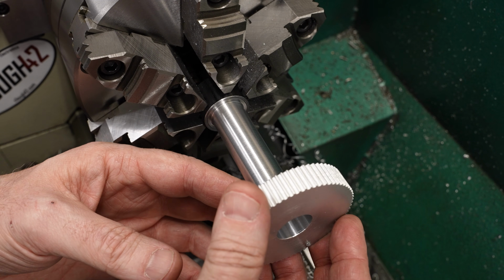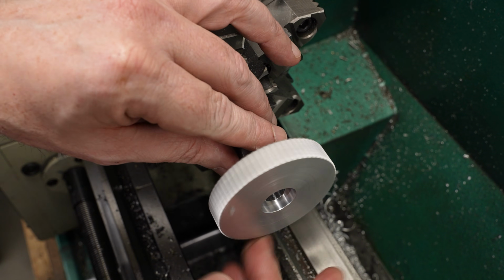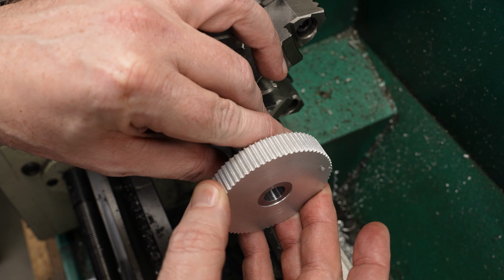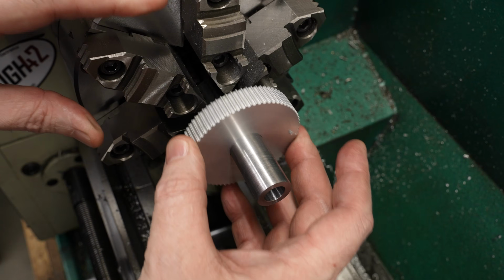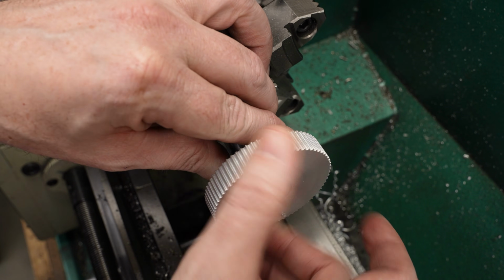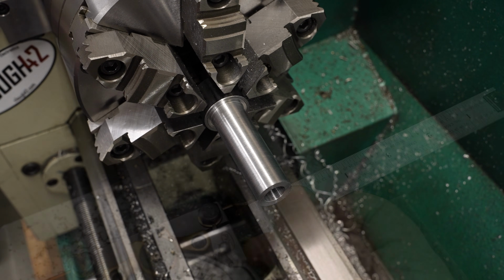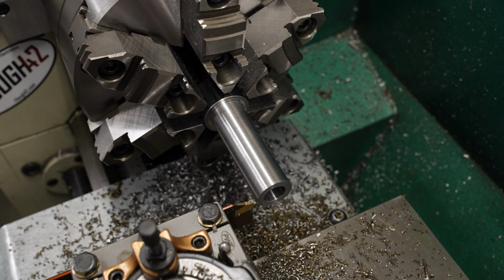And you'll remember that the pulley was slightly over, so there should be plenty of room in here for a retaining compound, but it should still be a pretty nice slip fit. And that feels pretty good. Yeah, I'm going to call that good. And there's not appreciable taper here at all, so we can put the pulley on either end when we're done.